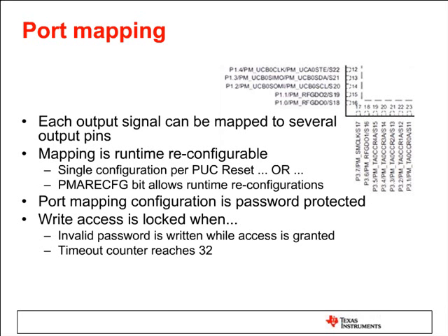And when I'm doing my layout, that can really reduce the constraints and the routing and maybe in some cases the number of layers that you actually have to use for your board, and that saves you money. So I think it's a neat feature for testing, for development, for the customization of your PCB design. I think it's just great. So any digital signal can be port mapped out to port 1 through 3. And it automatically locks itself, or you can lock it. It is password protected, so your application doesn't go nuts and then all of a sudden start changing up your ports.